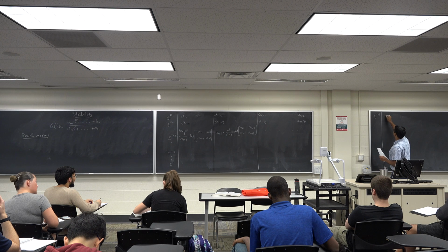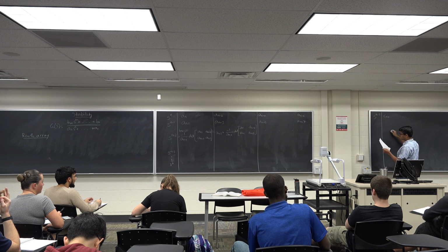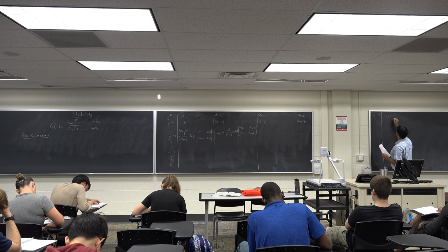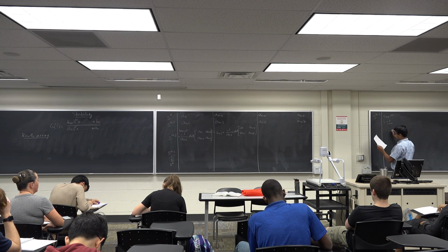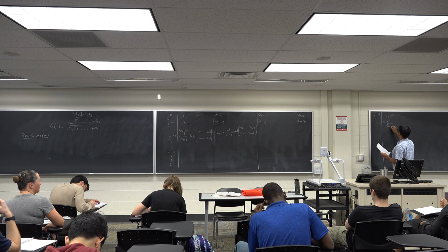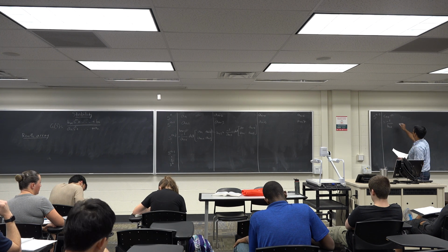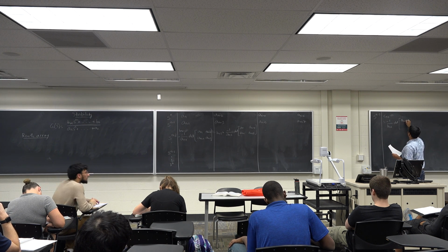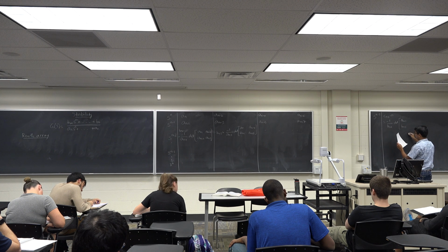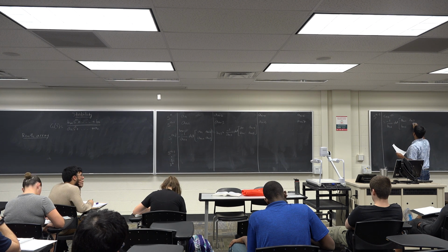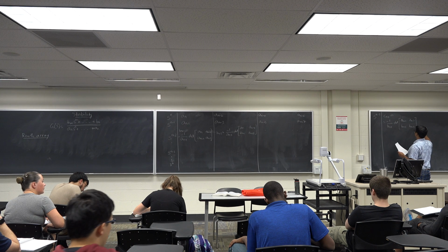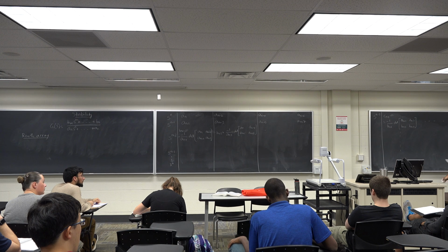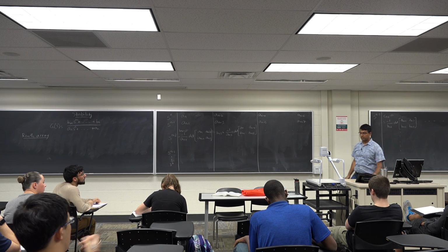So for Sn minus 3, I'll denote Cn minus 1 as equal to minus 1 over Bn minus 1, determinant of an minus 1, Bn minus 1, an minus 3, Bn minus 3, and then I can keep filling up this Routh array in the same fashion.